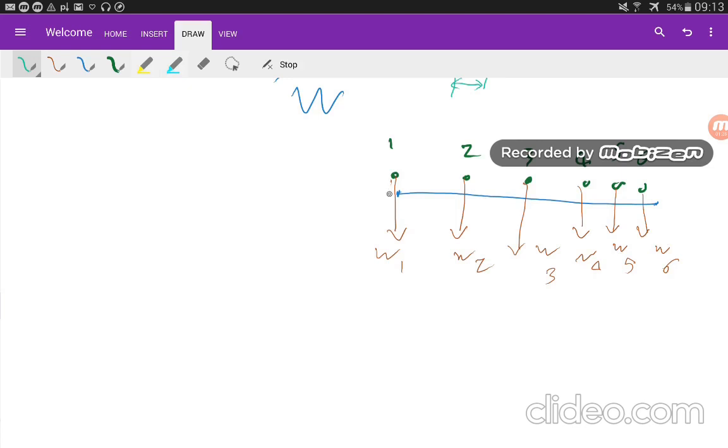We can assume any point on the lever as a reference point. You have to select a reference point. For the vessel, if I draw a vessel, we look at it from the forward, and this is the midship cross section. The bottom of the vessel is the keel point, and we name it K. All the time we use the keel point as a reference, which is the end of the vessel, because definitely you cannot load any cargo below the vessel on the sea.